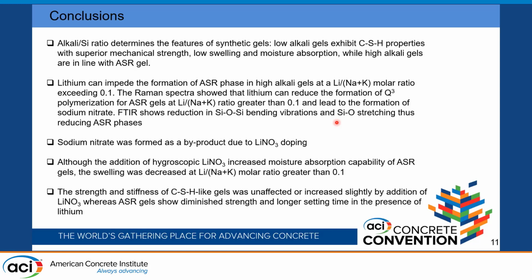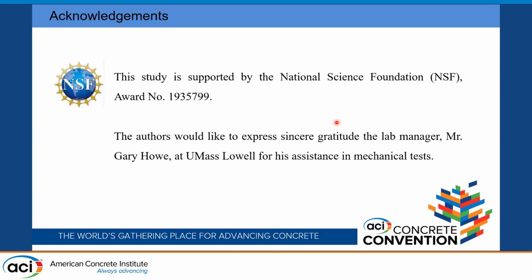Sodium nitrate was formed as a byproduct due to the lithium nitrate doping. And although lithium nitrate is hygroscopic in nature and its addition can increase the moisture uptake capability, the swelling is decreased beyond the lithium to alkali molar ratio of 0.1. The strength and stiffness of the CSH-like gels were unaffected or increased slightly by the addition of lithium nitrate, whereas the ASR gels showed a diminished compressive strength and longer setting time in the presence of lithium.